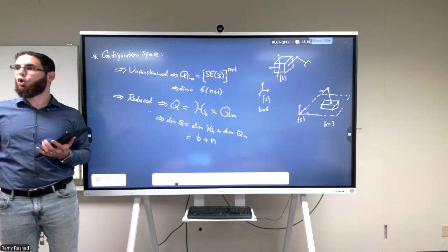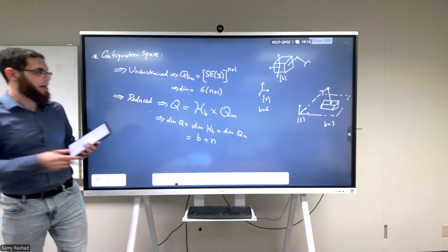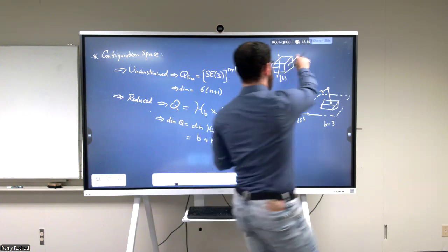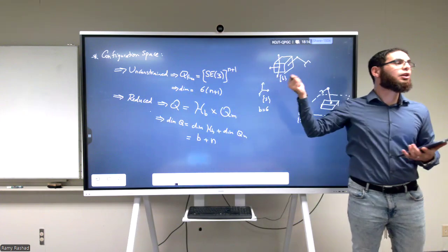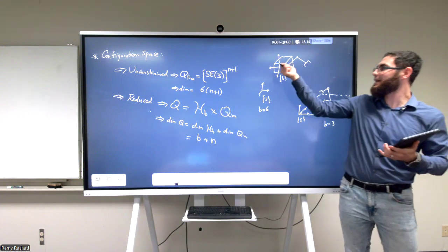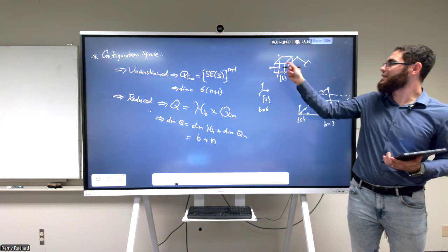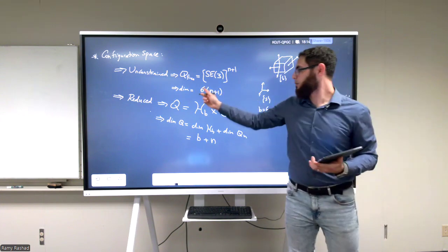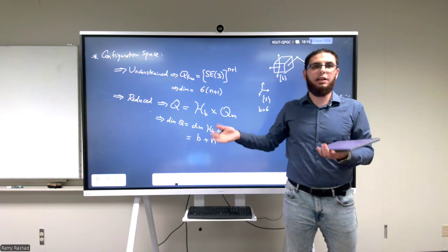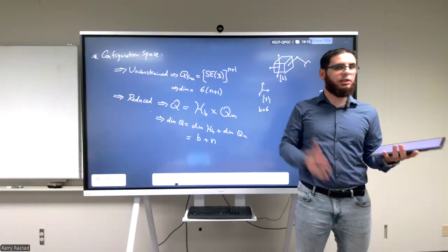So in the end, the joints that will be added, I have n joints that are in the manipulator, and I have one extra joint that will describe how the base is moving with respect to the S frame. And this joint will reduce the base movement from 6 to B. And in the end, if B is 6, then we did nothing. Right? This is just a generalization.